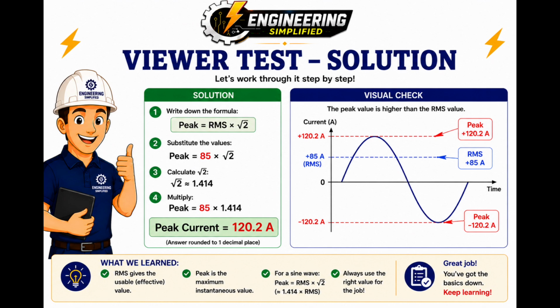We start with the formula. Peak equals RMS multiplied by the square root of 2. Our RMS current is 85 amps, so peak equals 85 multiplied by 1.414, and that gives approximately 120.2 amps. Therefore, an RMS current of 85 amps corresponds to a peak current of approximately 120.2 amps for a sinusoidal waveform.